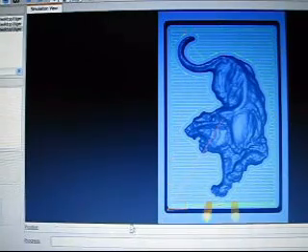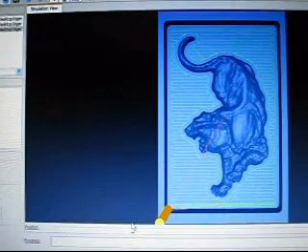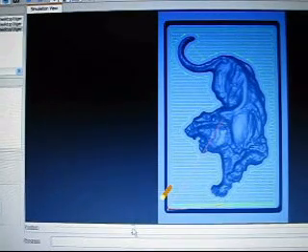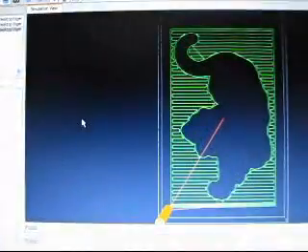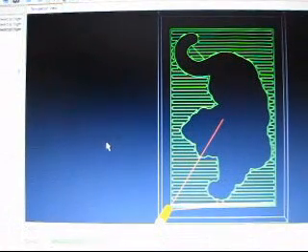After this tool, see how it just changed right there? Alright, the next step will be the tool change, which I believe is the M6. So I'm going to leave it right there. If I leave it back in that position and regenerate this, watch what happens. This is a pretty neat trick. I don't know if you know this, but it's kind of a neat thing that I just discovered myself. And let that generate.